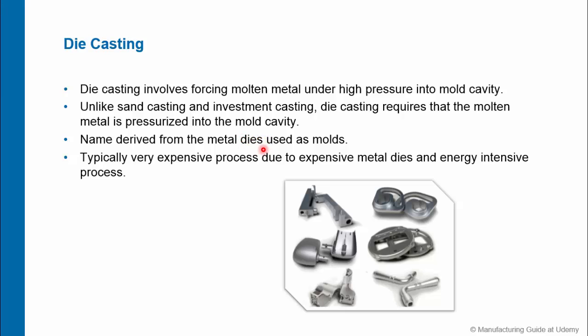Keep in mind that this is a very expensive process because of two reasons. First, the dies used in the process as molds are very expensive to make. Secondly, the process is very energy intensive because of all the high pressures and temperatures required in the process.